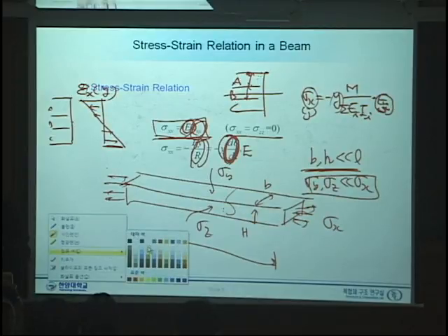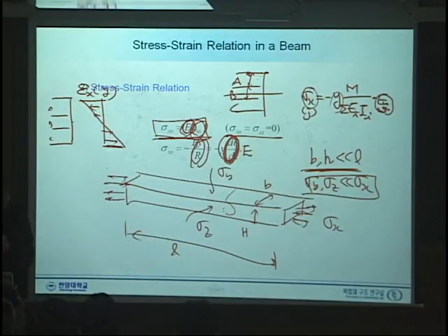Stress, how do you calculate the stress when you have this strain? Well, simply you need to multiply a material property, right? So you have three different layers. From here to there, which Young's modulus do you need to multiply to have stress? E_A, right? So let's multiply E_A. And since this is continuous, this stress distribution will be like that, right? So this is simply E_A times epsilon.